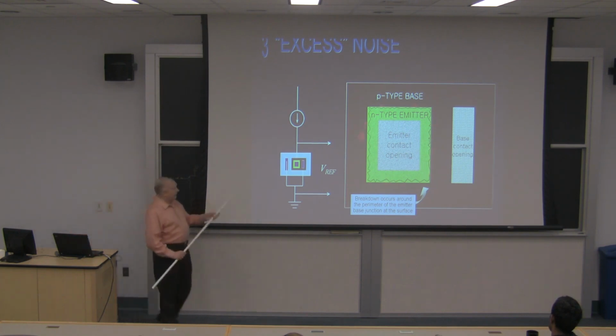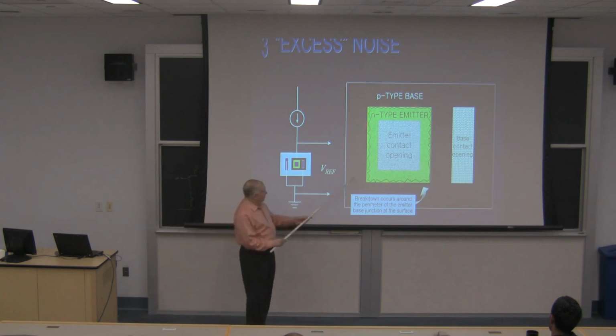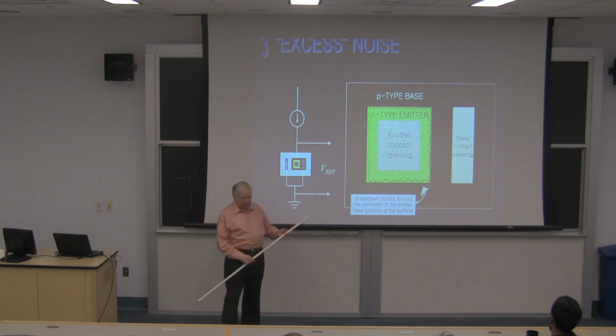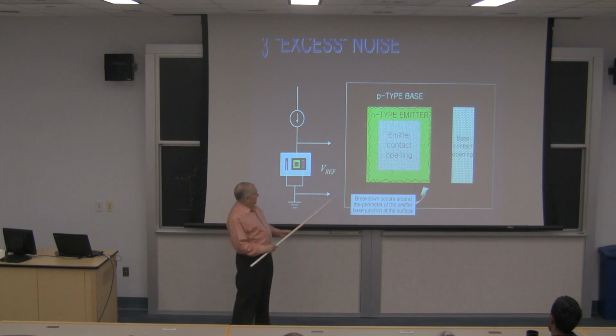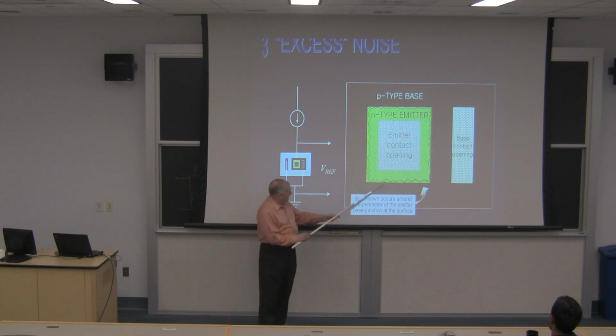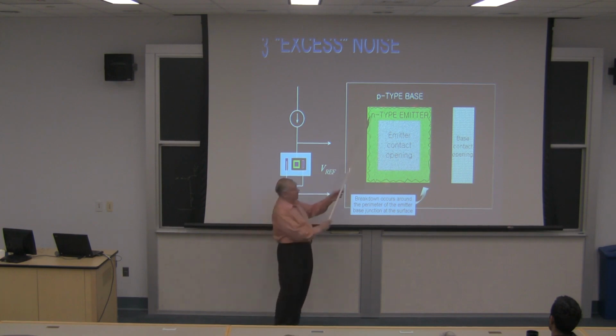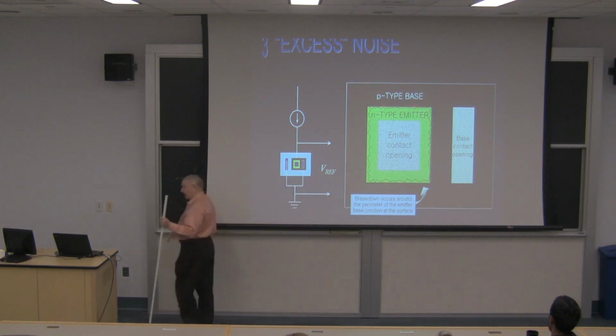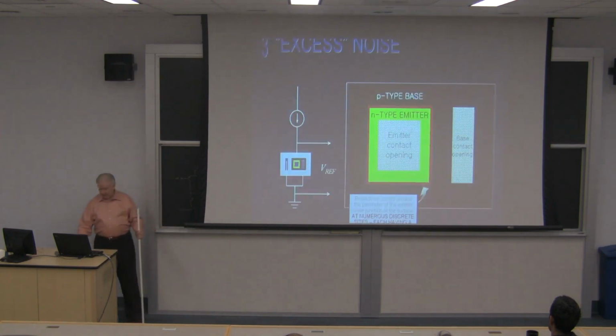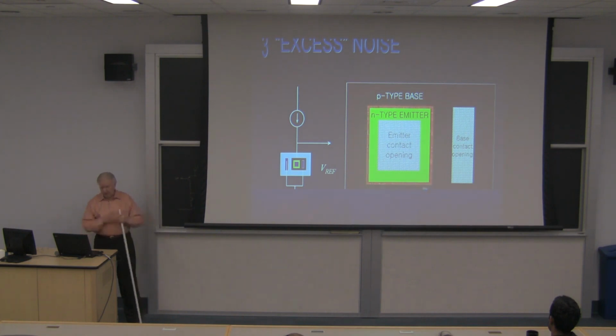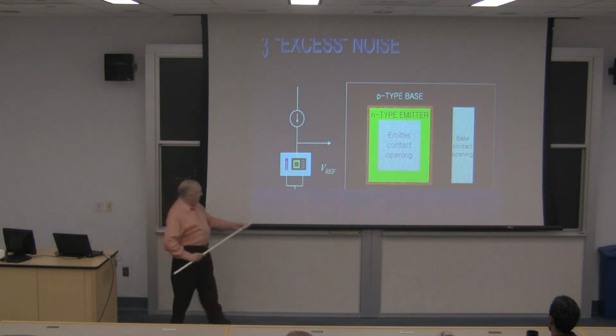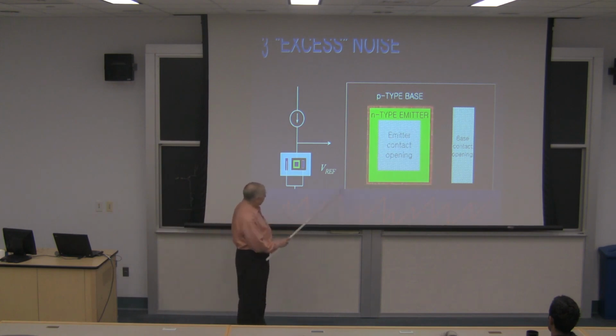Now, this earlier slide, I should have mentioned, was that in a typical breakdown above 5 volts, the older emitters just break down about 8 volts, the temperature coefficient of the breakdown voltage is positive. So when the domain occurs, it heats up that little region there, and the breakdown voltage goes up. So now the breakdown pops to somewhere else where it's more favorable. And so you end up with a peculiar kind of noise. So here's our emitter breaking down over the map. And we end up with a sawtooth of noise, because you can see the voltage is rising as the local temperature rises at, I think, one of these points, and then suddenly another point takes over and it drops back down to the lower voltage again.